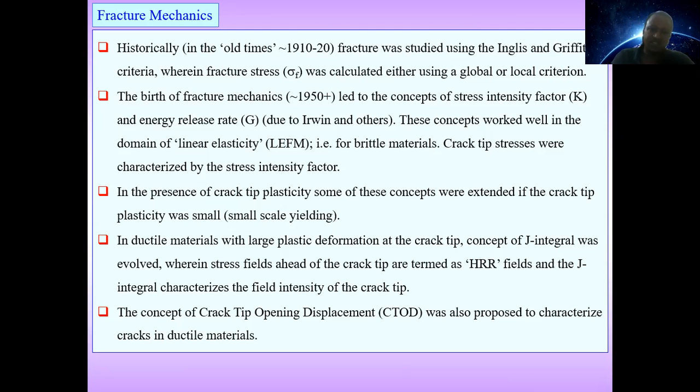In ductile materials with large plastic deformation at the crack tip, the concept of J integral evolved, wherein the stress fields ahead of the crack tip are termed HRR fields, and the J integral characterizes the field intensity of the crack tip. The concept of crack tip opening displacement, CTOD, was also proposed to characterize cracks in ductile material.